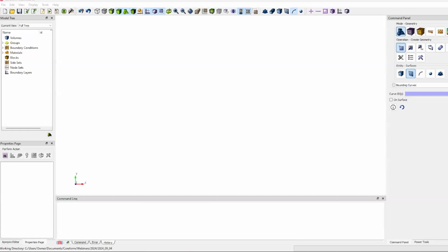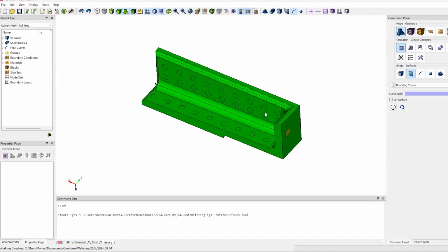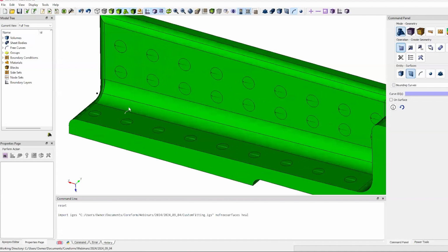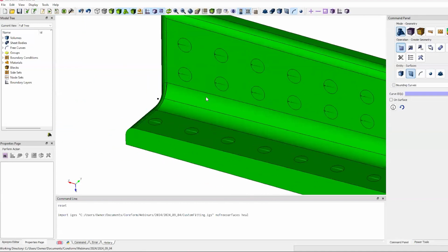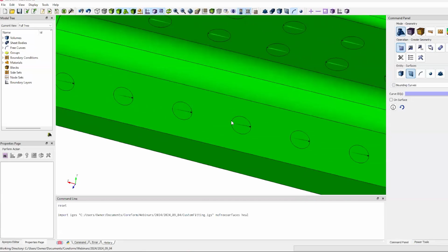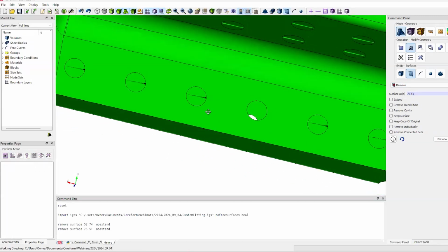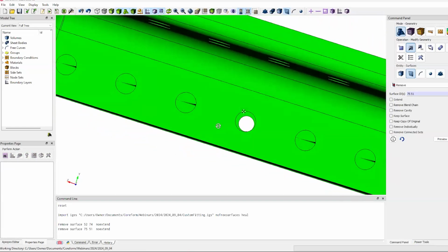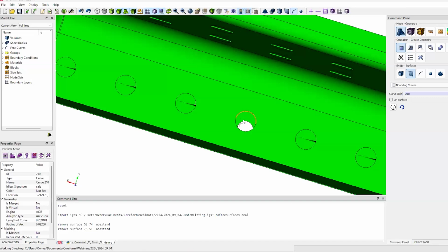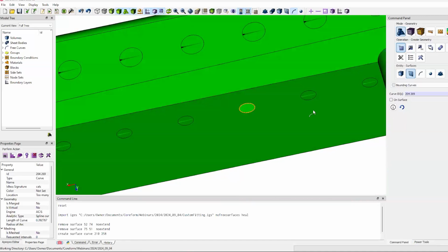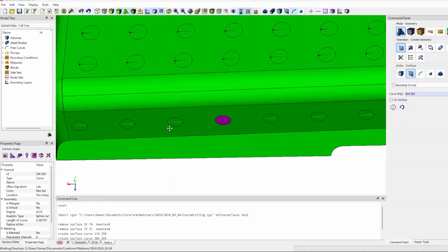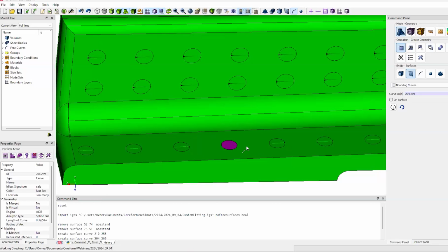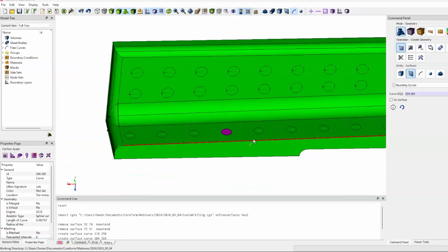But just to motivate this a little bit further, in this case this is the IGES file, where you can see there are some things like some free curves, or that these bounding surfaces for these holes are damaged. There is the ability in Cubit, again, maximum power to the user, to come through and specifically clean up your geometry so that you can then reconstruct quality CAD. So in this case, being able to delete those surfaces and then create new surfaces. And if you do that for all of these holes, you can then reconstruct, add the chamfers, do the removals. You can reconstruct this geometry.